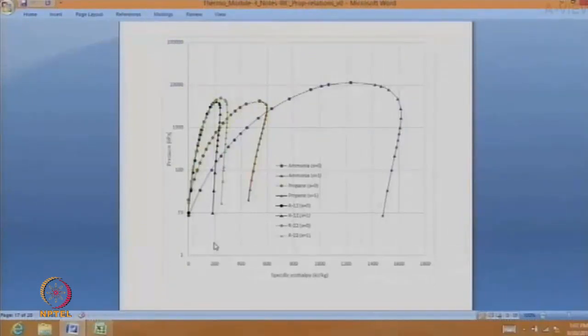We have propane, we have butane, we have R22, 23, 14, so many hydrofluorocarbons. And we start looking at all the properties and we find two materials which are very similar in properties, we can substitute them with one another provided all the other things don't come in the way. For example, there's no corrosion or reaction with the oils, or it doesn't become toxic, otherwise we won't use it.